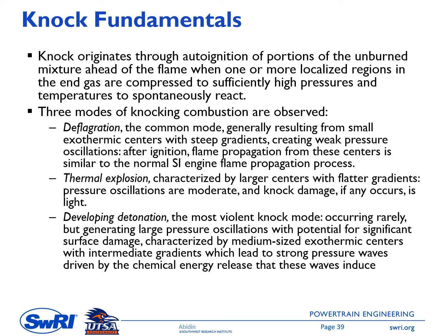So, knock originates through auto-ignition of a portion of the unburned mixture ahead of the flame, when one or more localized regions in the end gas are compressed to sufficiently high pressure and temperature to spontaneously react. There are three modes of knocking combustion observed. One is called deflagration. This is the common mode, generally resulting from small exothermic centers with steep gradients. This deflagration mode is similar to the normal SI engine flame propagation process.